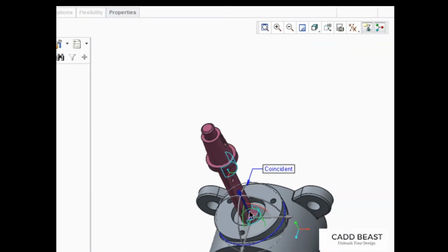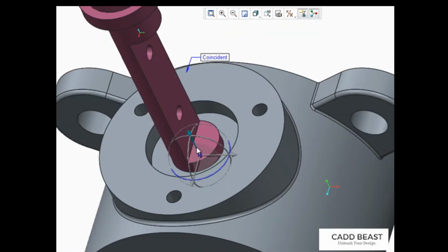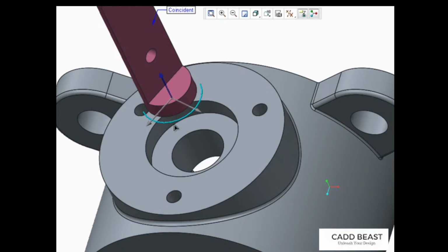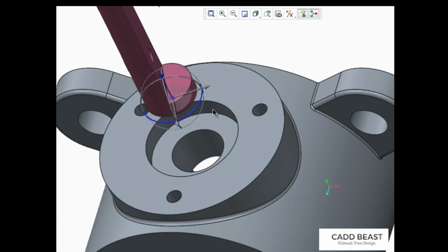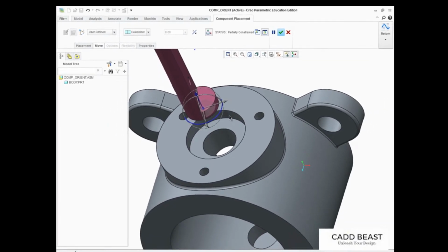An example is a shaft inserted in a hole, which limits motion to only one rotational axis and one translational axis, which are the shaft's remaining degrees of freedom. The new 3D dragger provides you with an easier, more interactive method to move your components about in assembly, while respecting the limitations of the constraints you've specified.